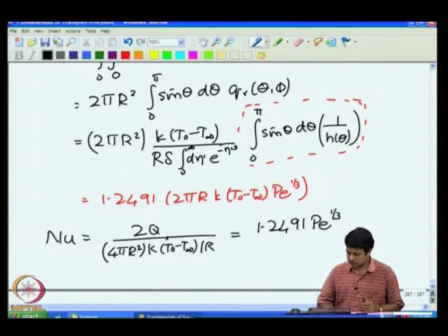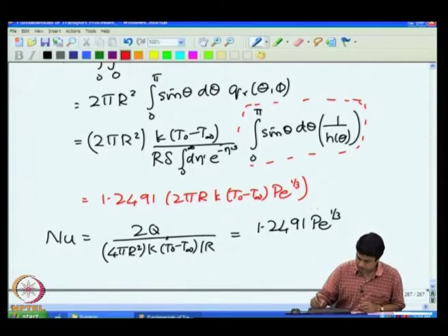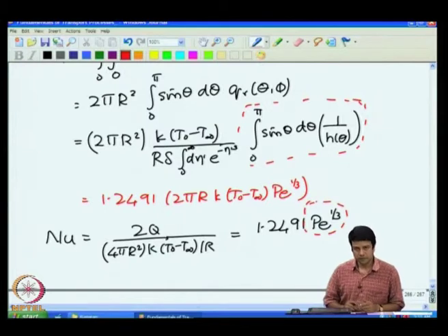And this is because we have heat transfer at a solid surface. The velocity field in the fluid at that surface has to decrease to 0 at the surface itself. So, it has to increase linearly with distance away from the surface. And if the boundary layer thickness is small compared to the macroscopic scale, I can use a linear approximation for the velocity field near the surface. So, this result is a general result which holds for any form of an object with flow past it, provided the velocity is 0 at the surface itself, and it increases from 0 very close to the surface.